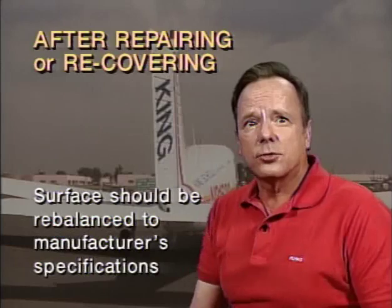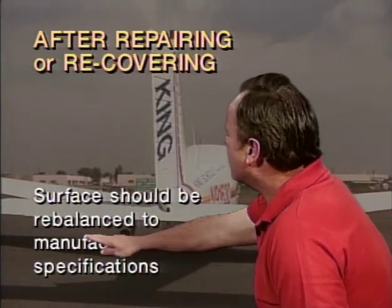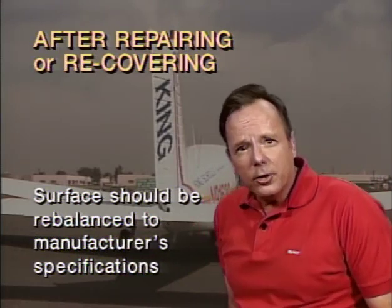Now let's assume as a mechanic you've done some work on the rudder of an aircraft. Maybe you've repaired it or recovered it. What should you do next? And the answer is you should balance the control surface according to the manufacturer's specifications, because if it's not properly rebalanced, you could have control system flutter. Now, how do you go about rebalancing it?